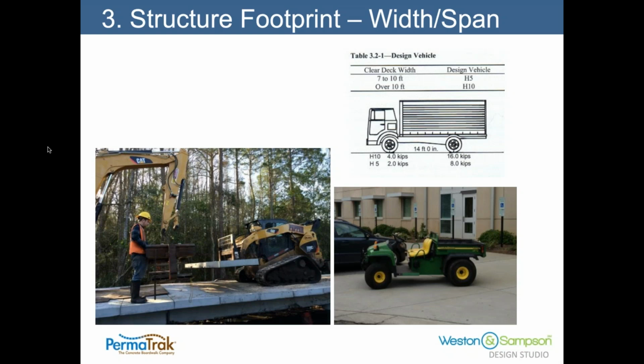Also, there are regions in the country where we've designed boardwalks where there's significant snow load. We've designed structures out in Lake Tahoe, and there's certainly heavy design snow loads there, and they could be 100 or 120 pounds per square foot just in the snow load. So you have to compare that regional design requirement to what's in the LRFD pedestrian bridge guideline.